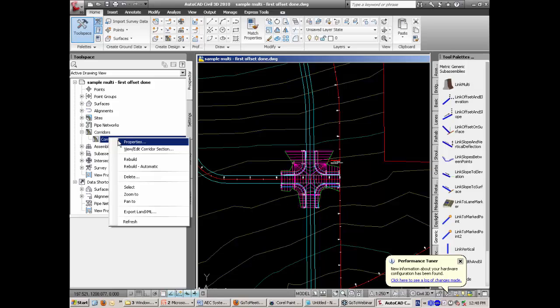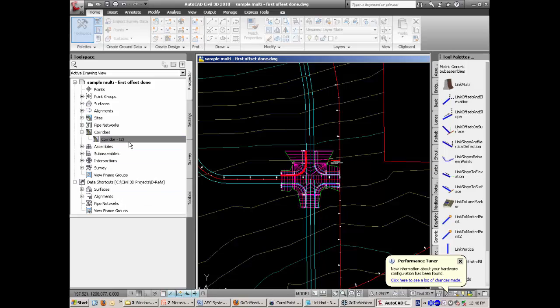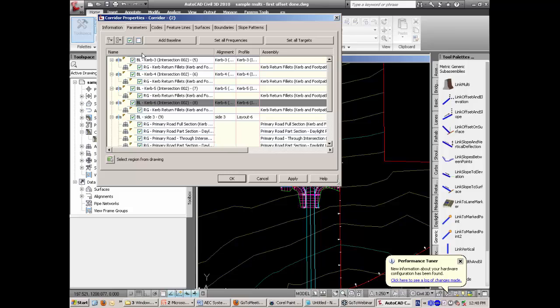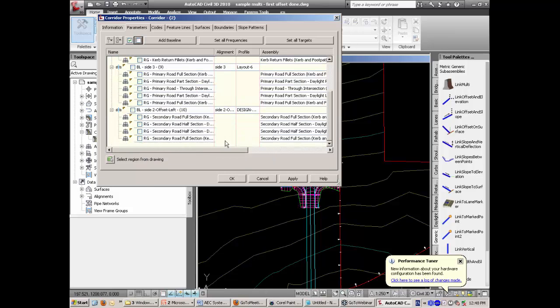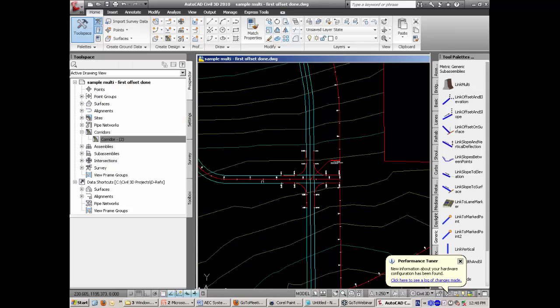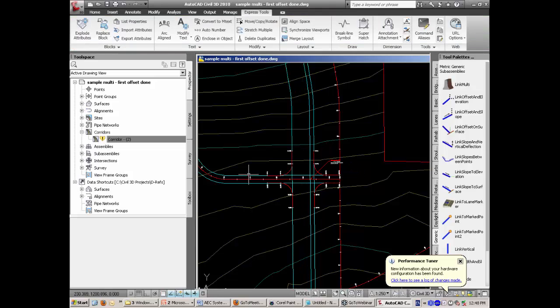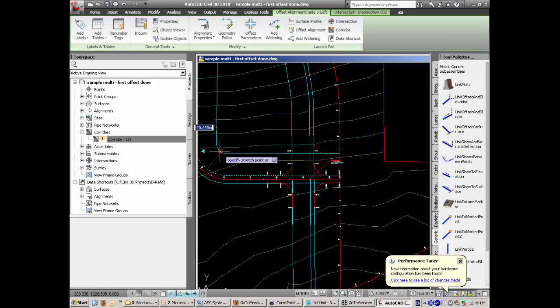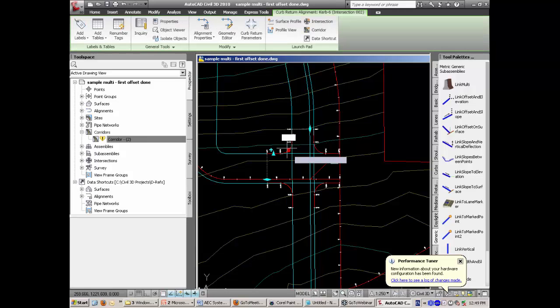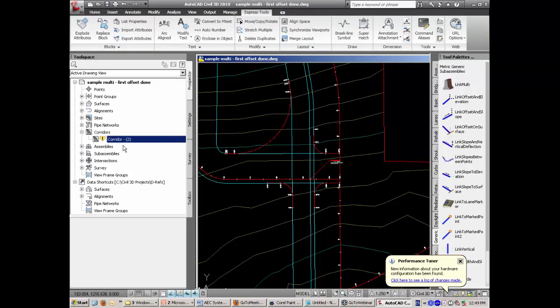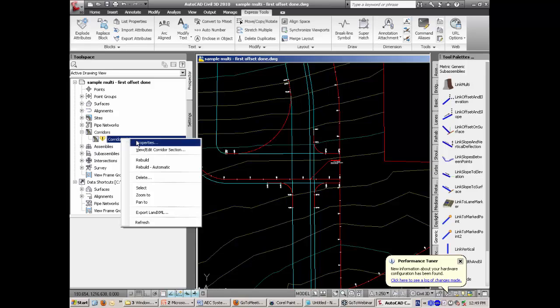And so first of all, leave the software, chuck in the defaults, go to your corridor model on my left hand side here, go to my properties, go to the parameters. These are all the regions the software creates. I'll just turn all these off. Press OK. So my corridor model still exists. I can now go and start doing all my work to get my horizontal geometry worked out. The software isn't calculating the corridor. It'll work nice and fast.